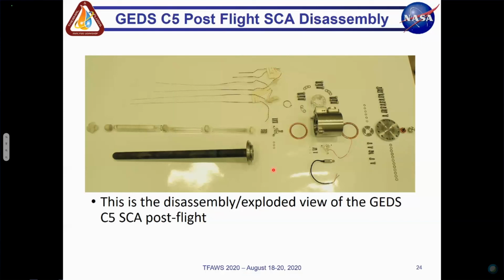So the two theories are that it's embedded gas in the porosity of the cartridge itself, buried inside the molybdenum, or that it's molybdenum oxides dissociating. I don't know the correct term, but once it gets to certain temperatures, the oxygen separates off the molybdenum. At lower temperatures, it's volatiles and any liquids that are on it. There shouldn't be, but it's pretty obvious that there are.